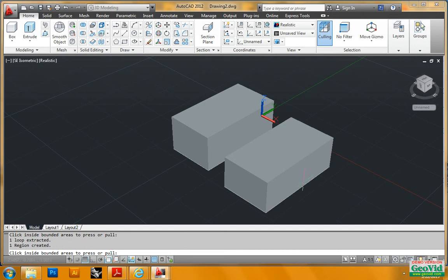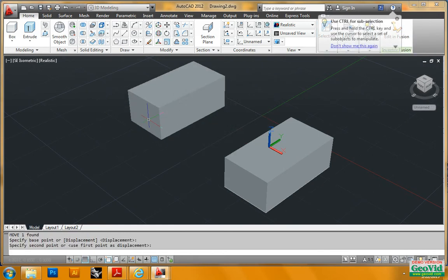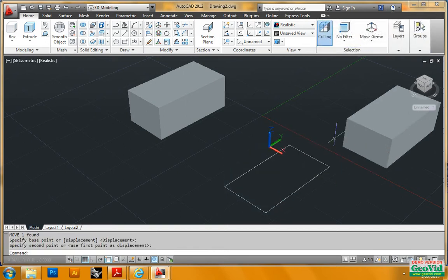So they look pretty similar, however with the extruded box, which is right here, if you move it, your baseline has disappeared, whereas with the push-pull box, if we move this, you can see that the square is still there. I personally like push-pull because it keeps your baselines. However, it is always smart to copy and paste your baselines or any of your line work over into the side of your view for future reference in case something happens and you can't get back to the beginning because you went too far ahead.